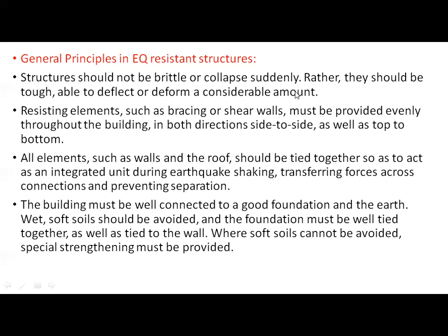In the first point only, we have learned from this Unit 1, the first point we have discussed, that is the load path. Load path is the path through which whatever load is transferred from the top to the soil. So each and every element should be tied with each other, and then they can transfer the load towards the foundation. For that purpose, we should take care that each and every component should be tied with each other.